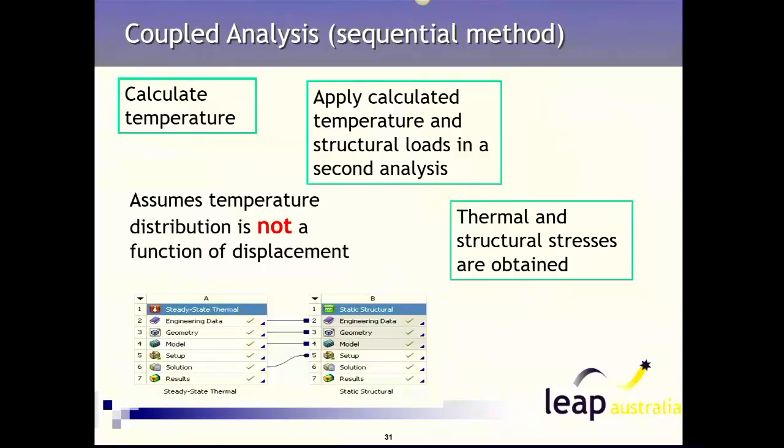So you can impose mechanical loads on top of thermal loads, and if your temperatures are non-uniform, you can't just apply a constant temperature to your parts. You have to calculate that separately. Because your thermal deformations don't really affect your structural loads, you can calculate them separately.